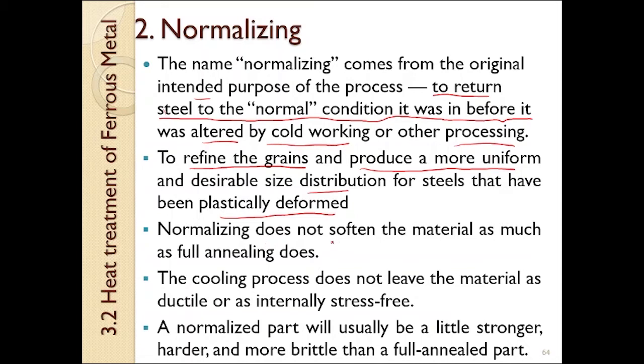Normalizing does not soften the material as much as full annealing. The cooling process does not leave the material as ductile or as internally stress-free. A normalized part will usually be a little stronger, harder, and more brittle than a full annealed part.